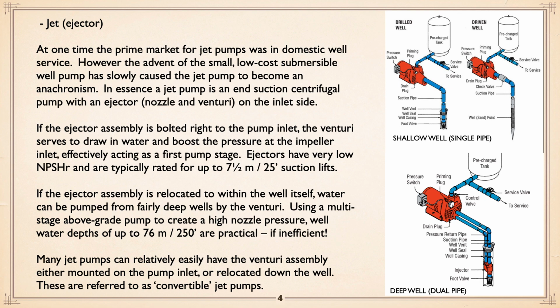When the inlet is bolted to the pump, the pump has a little throttling valve on it. You have to prime it, fill it with water, and that allows it to pick up pressure, and it goes around through the inlet venturi, and that draws water up from below because that venturi, as I say, is playing like a pump.